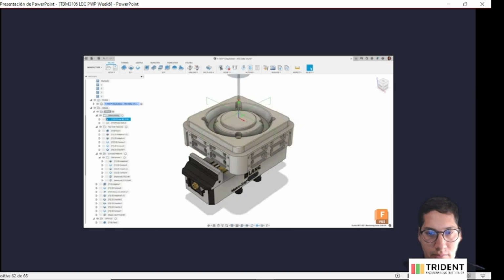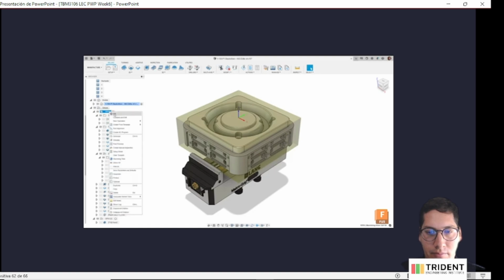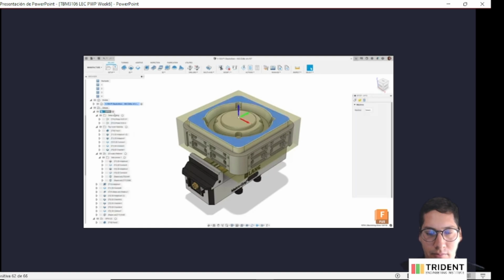In this example, I have already pre-programmed a set of toolpaths for this part and want to get a good idea of the machine movements prior to running it on a physical machine. Right-clicking on the setup and clicking Edit will expose the setup dialog. From the machine section within the Setup tab, we can choose the Select button, which will open the machine library